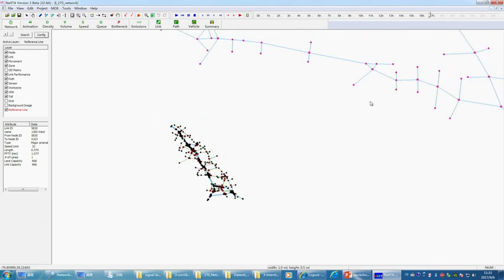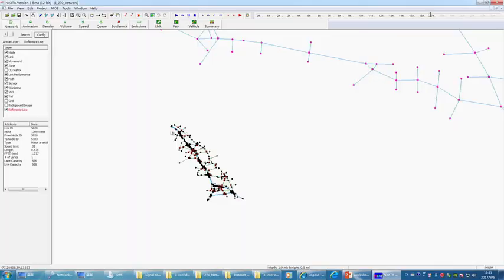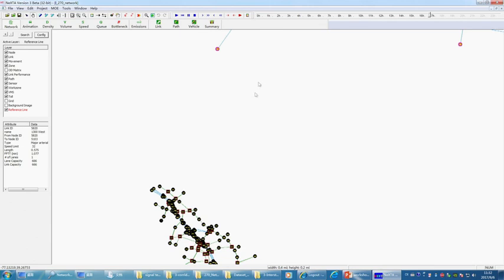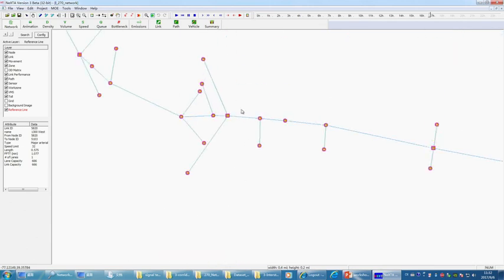So some users may ask me to have a fully automated process for this mapping function, but we look at the reality. Many networks might have a very different network structure, so we still encourage the users to do this manually to compare. One is a DTA node number, the other is the Synchro node number, so that you can combine these two networks in a much more systematic way, because any error you make in a signal representation might create very unrealistic traffic queue spillback.